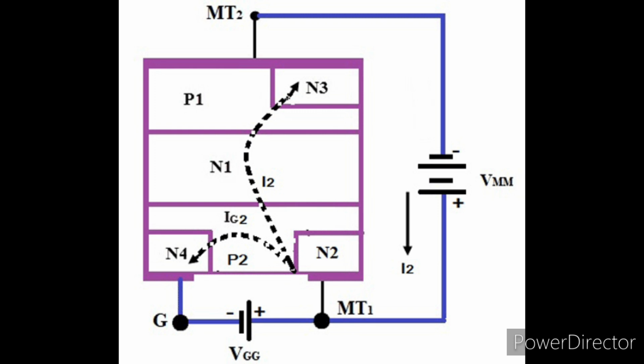the P2N1 junction, and since the P2N1 junction is forward biased, the width of the depletion region is very small, so the electrons reach N1 and then obviously N1 becomes more negative compared to P1, and so the width of the depletion region due to reverse bias gets decreased and the device now conducts and the current path is P2, N1, P1, N3. Note that the triggering of mode 1 is more sensitive among all the modes because in mode 1 a smaller gate signal makes the TRIAC on.